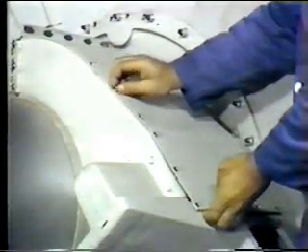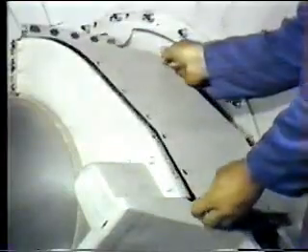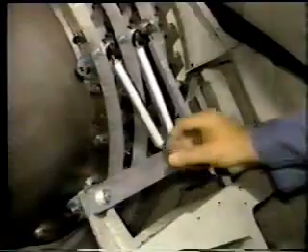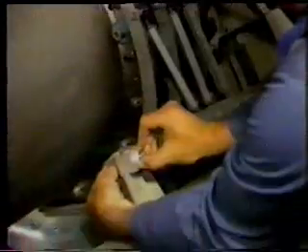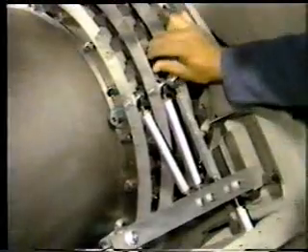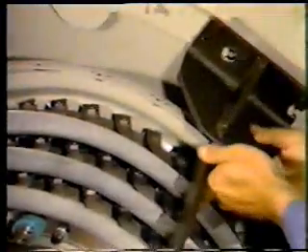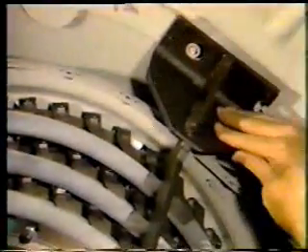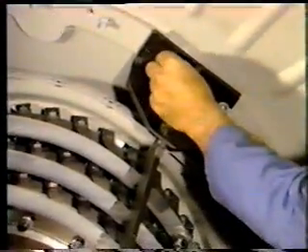Remove the bolts and sheet metal enclosures from around the variable guide vanes. Inspect the assembly for contamination and loose parts. Make sure that all of the components are securely tightened. Next, remove 2 bolts from the air inlet housing for the gauge. Now the gauge can be installed over the scales. Begin by placing the gauge over studs and tightening the bolts finger tight.